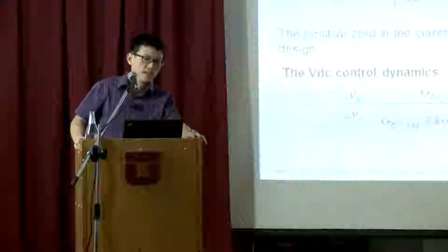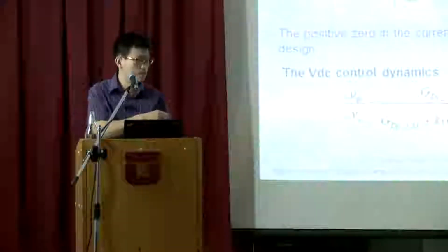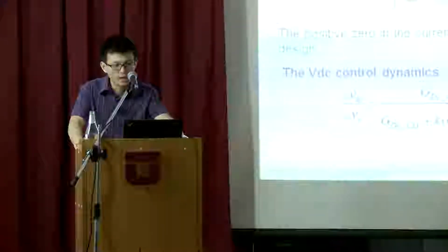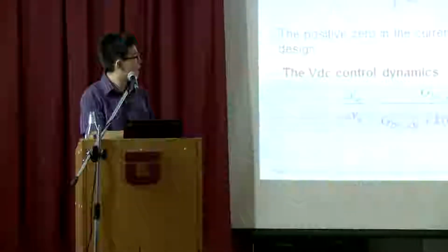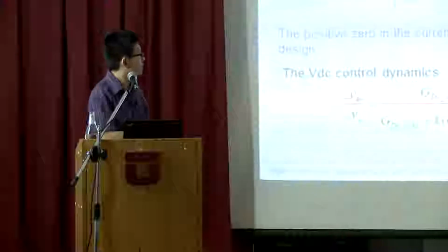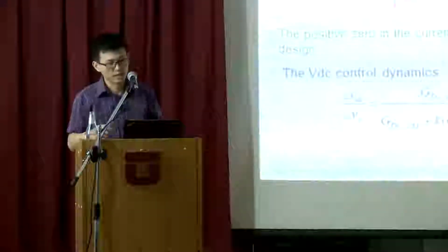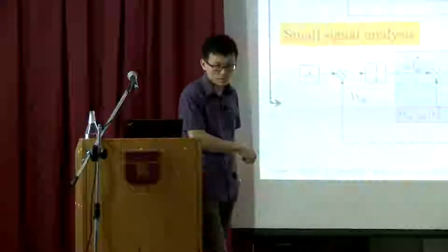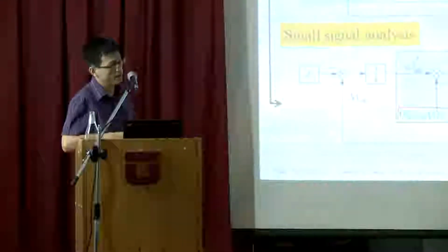So when you go back to do your microgrid analysis, you should be very careful when you design this inner loop, the IDC control loop. You might end up with a different conclusion, because here we use the electrical drives. For you, maybe you use the PV panel, maybe different. But this is something you should be aware of. The method we're using, as I said, is small signal analysis, and the way you derive this, of course, always starts from this kind of single line diagram.